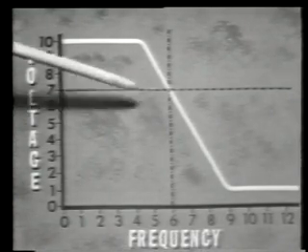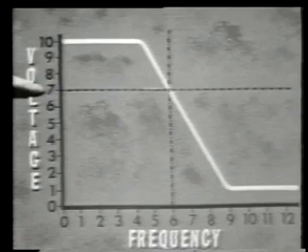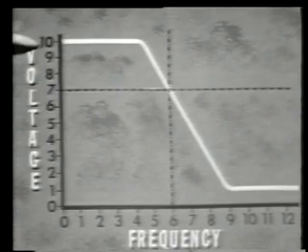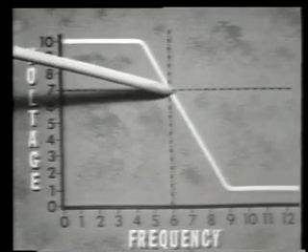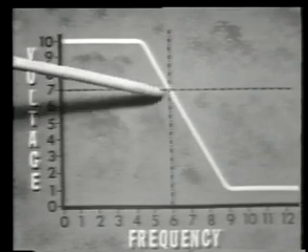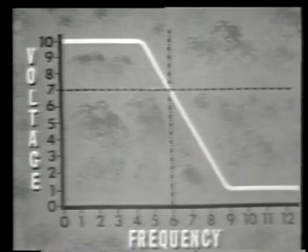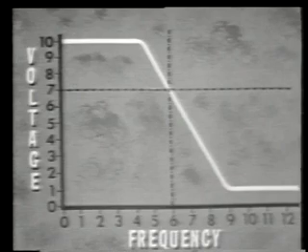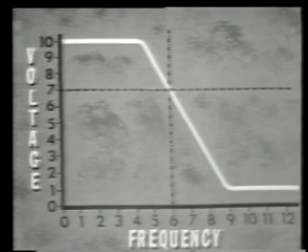Here, at about 600 hertz, the output drops below 7 volts. Now remember, I had an input of 10 volts. So anything in the output less than 0.707 of this 10 volt value, or in other words about 7 volts, is not considered usable output from this filter. However, this is not true in all cases. Actually, the output voltage from the filter is still considered usable if it operates the load device. But in most cases, the output voltage should be at least the effective value of the input voltage.